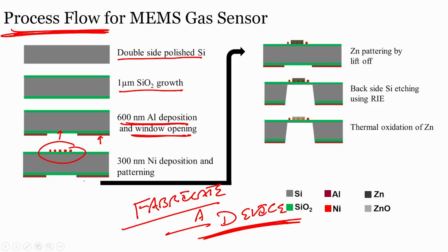On the nickel micro heater you can have electrodes. This is just an electrode, there is no heater here, but actually there is a nickel deposition. So, this is a heater. After this particular process, we have this nickel micro heater, on which there is an insulator, on which there are interdigitated electrodes, on which there is a sensing layer.